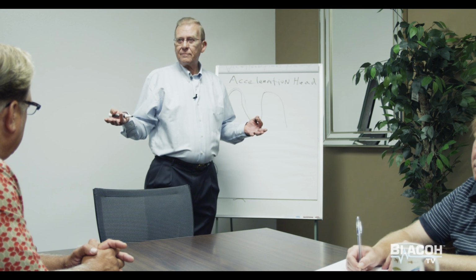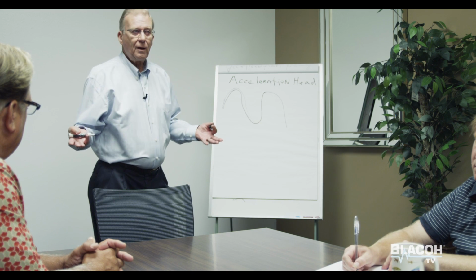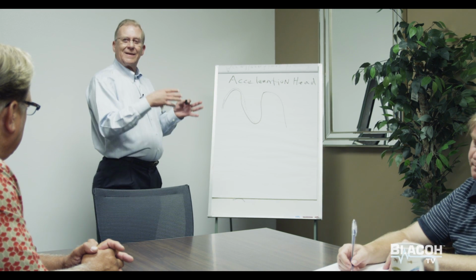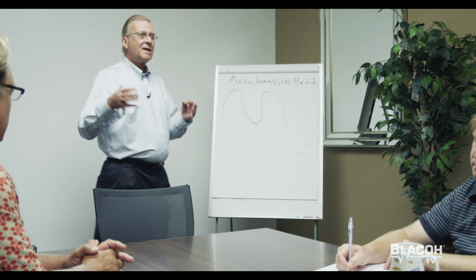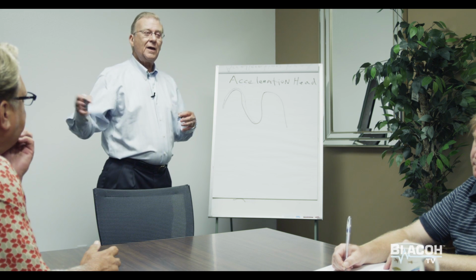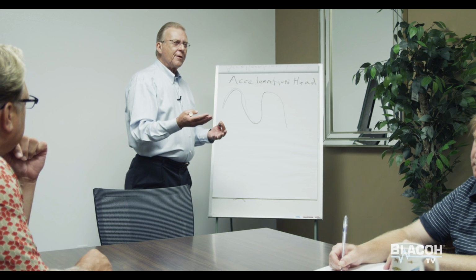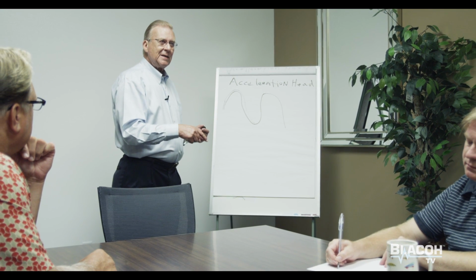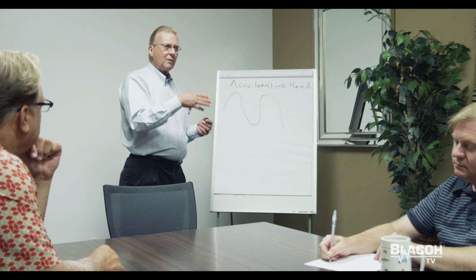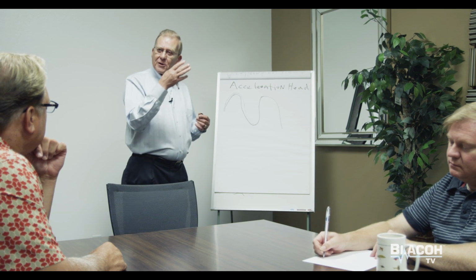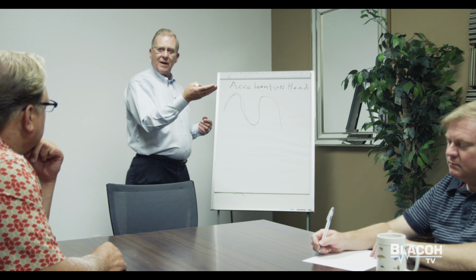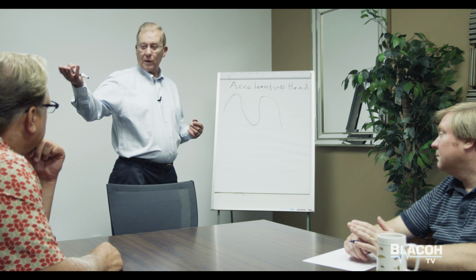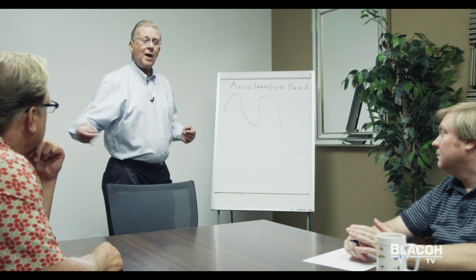Centrifugal flow, if you will, like out of a faucet. In other words, once you get the liquid moving, it stays constantly moving, takes less energy once it's moving. When you start a centrifugal pump, there is a peak of power used to initially get the liquid moving. Then that peak energy drops down to an average flow or average energy use as the product's flowing.